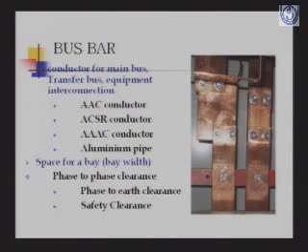The bus bar will have many schemes like single bus bar scheme, main and transfer bus bar scheme. You have various schemes, but generally in 33 by 11 kV substations we have double bus bar or single bus bar.